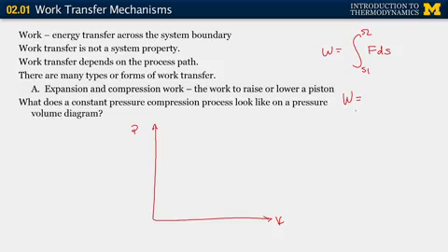And we said for expansion and compression work in particular, we would move from state 1 to state 2, and that the form of the expression was pressure times the differential d volume. So remember, the V with the crosshash is a volume expression. Okay, so that's our expression. If we have a constant pressure process, we know that that pressure is constant, and we know from our math that we can take the pressure outside of that integral. The state conditions here are now volume at state 1 and the volume at state 2.